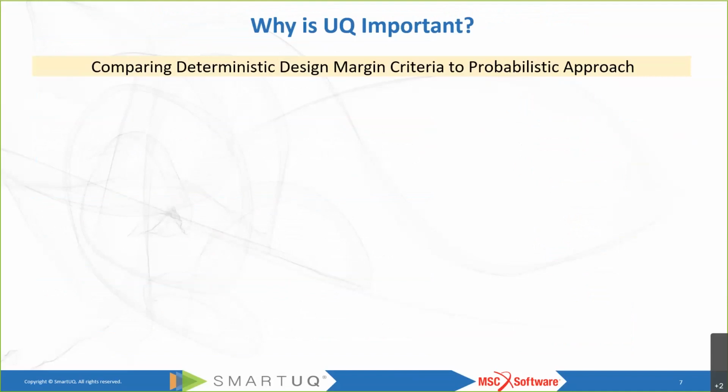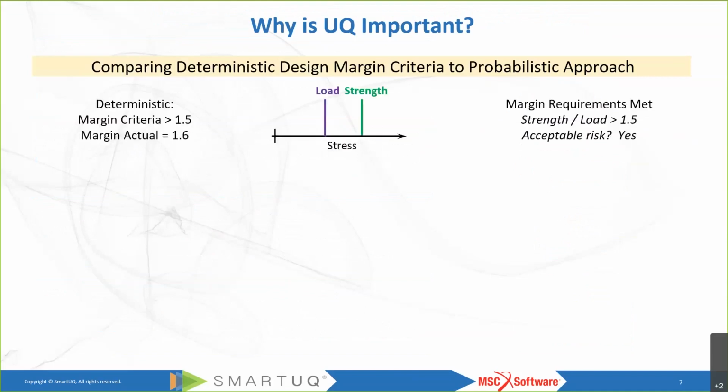So what then is the benefit of having access to probability distributions of outcomes and accounting for uncertainties? Uncertainty in engineering analyses has typically been handled using design margins. So for some specific loading condition, the component gets designed to have a strength that meets that loading condition, and then some additional factor of safety is added on top. The additional factor of safety is typically determined using historical precedent or engineering judgment or a combination of those.